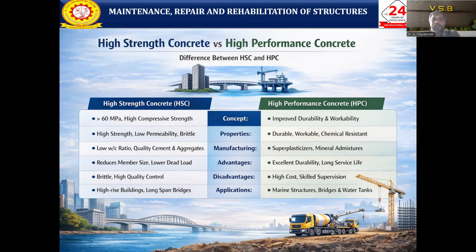Its manufacturing uses a low water cement ratio. The quality of the cement and aggregate is very important. For high performance concrete, various superplasticizers and mineral admixtures are available in the market. We need to use them to increase performance.